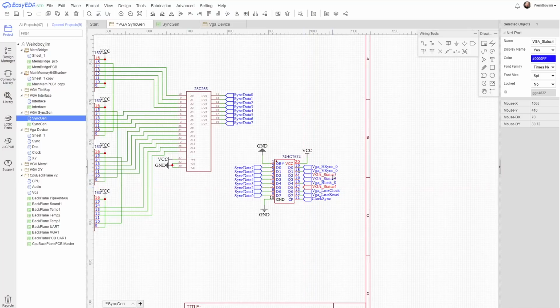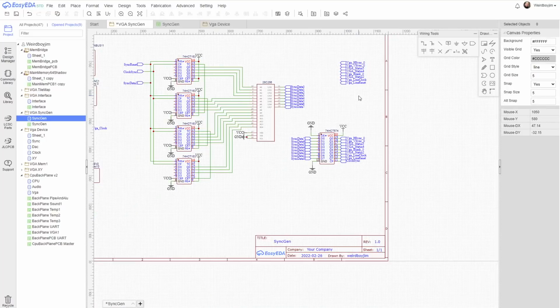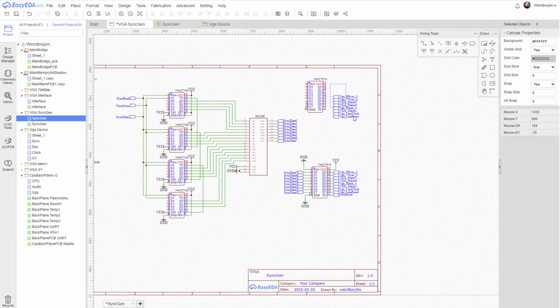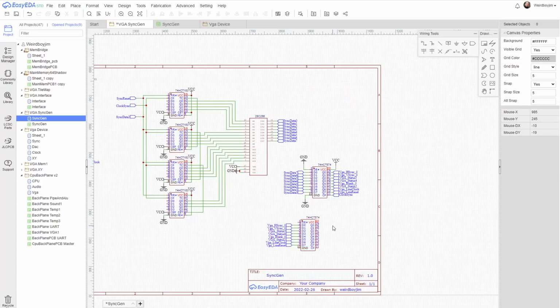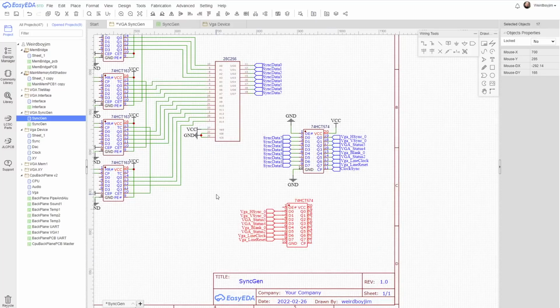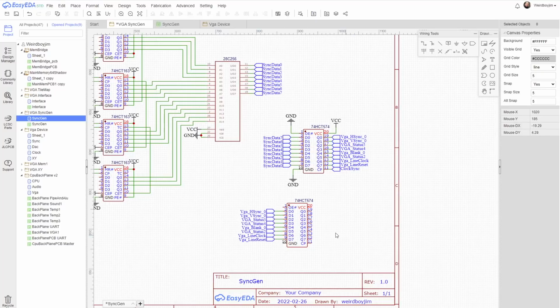Now the horizontal and vertical blanking interval, we don't actually use these outputs apart from in the status readback. Now what's bad is in the breadboard version we actually use a 541 to drive this data onto the bus on demand, and that's actually not the right thing to do.